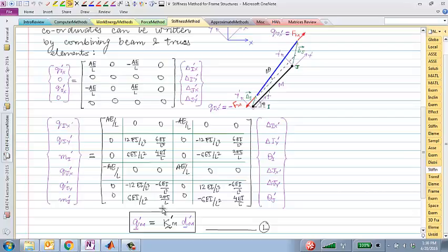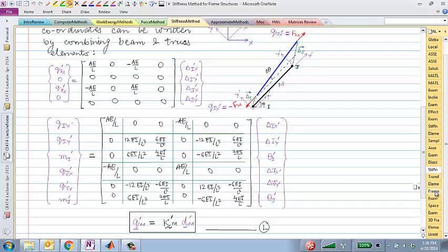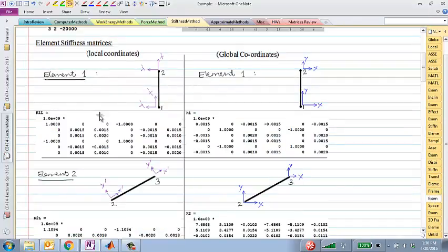So we allow MATLAB to compute all these numbers for us, and hopefully, a quick check, of course, would be that the zeros are in the right positions. Let's check. Yep, zeros out there in the second, third, fifth, and sixth columns of the first row, and so on. So that's the local element stiffness matrix using the expressions that we developed. MATLAB computes that very easily. And then how do I transform it to the global coordinate system?